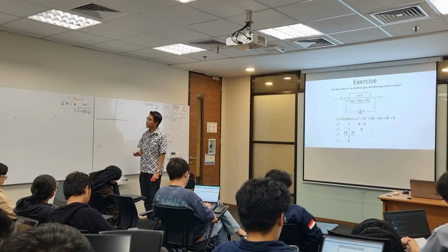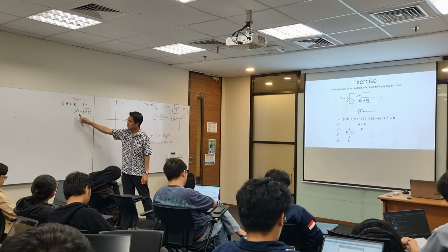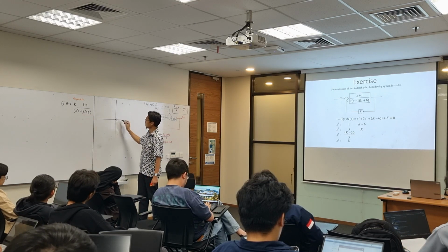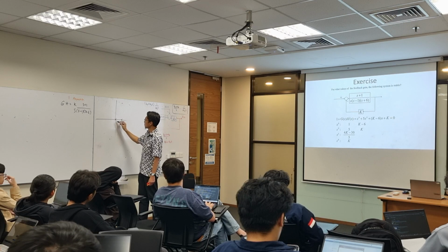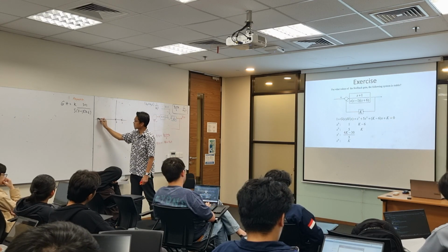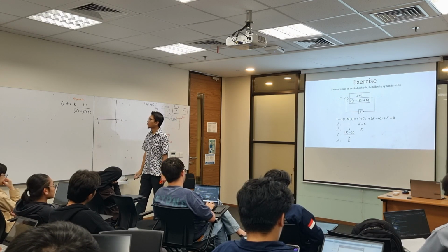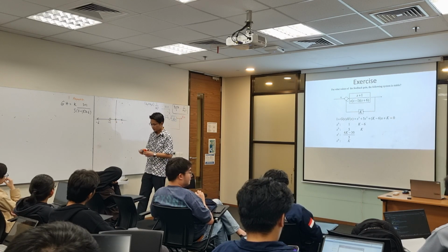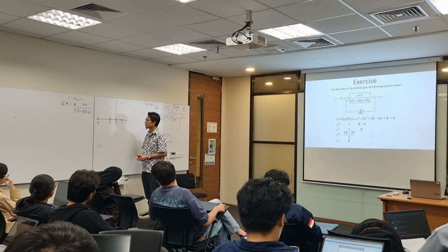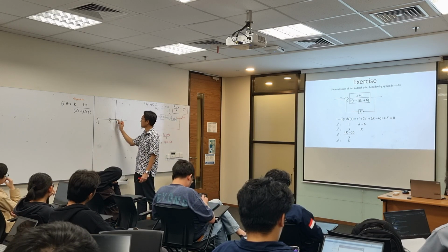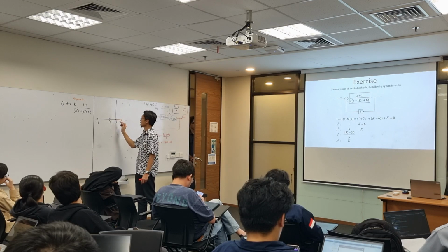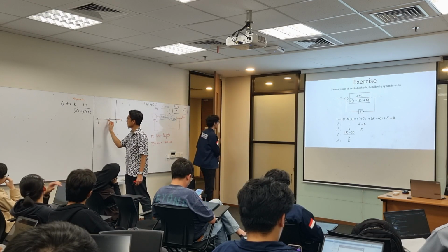Now open loop poles are 0, plus 1, and minus 6, and open loop zero at minus 1. In this case we will have root locus here, and then another root locus here.